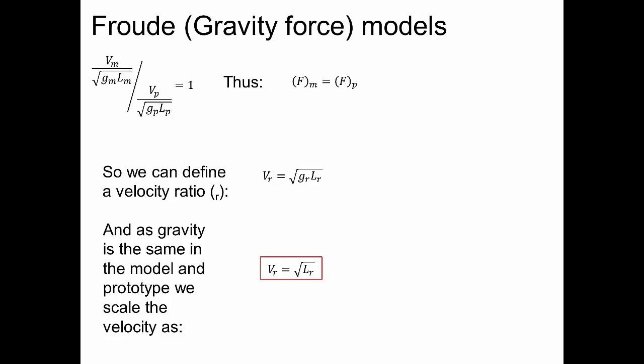So in my work with the tidal turbines, I have to scale both the channel, the water channel they're in, but also the flow across the devices, and they're underwater. So I have to use the Froude number and the Reynolds number as two of my main scaling tools. So what we're saying is that we're going to try and keep the same Froude number. So this dimensionless ratio, we're going to try and keep that the same in the model and in the prototype.